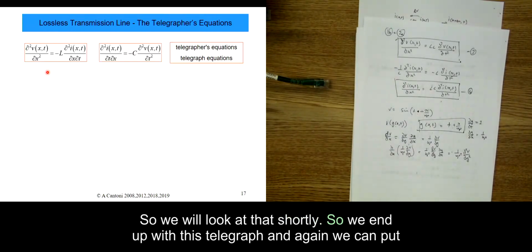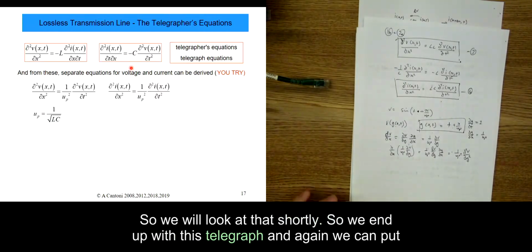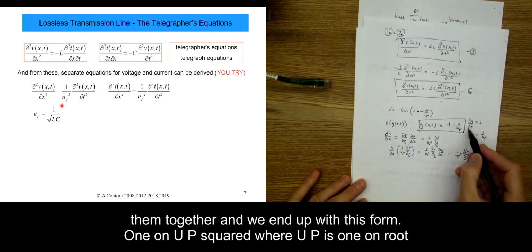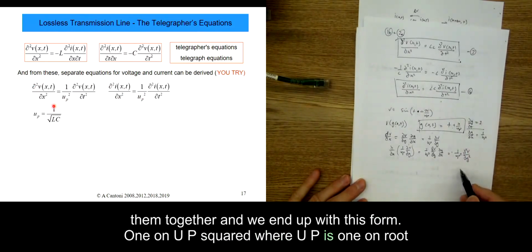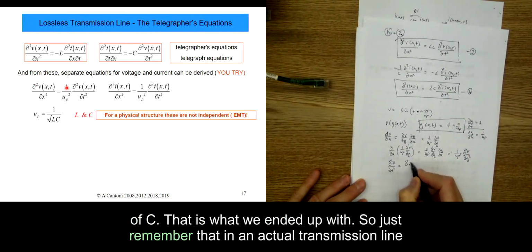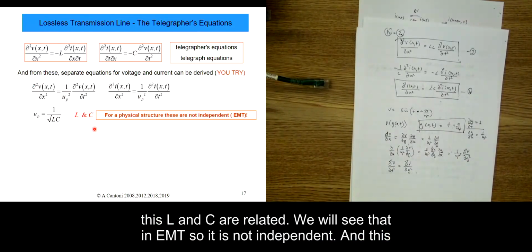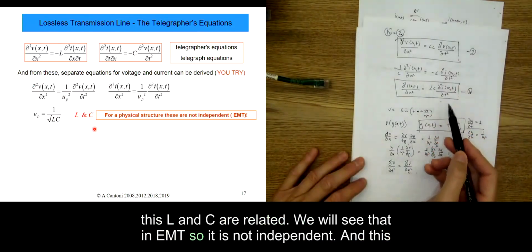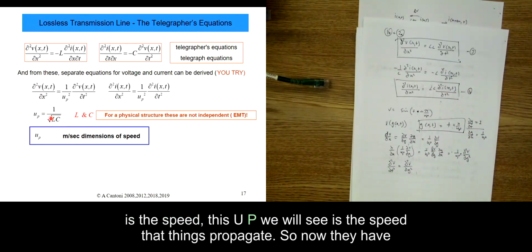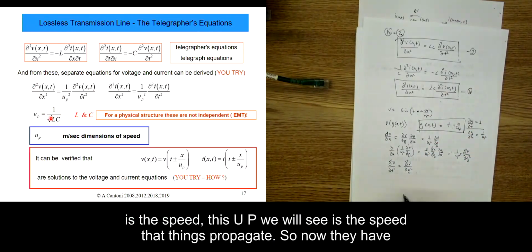So we end up with the telegrapher's equations as well. We can put them together and we end up with this form: 1 over u_p squared, where u_p is 1 over root LC. That's what we ended up with. Just remember that in an actual transmission line, this L and C are related. We'll see that in EMT, so it's not independent. And this u_p is the speed at which things propagate.